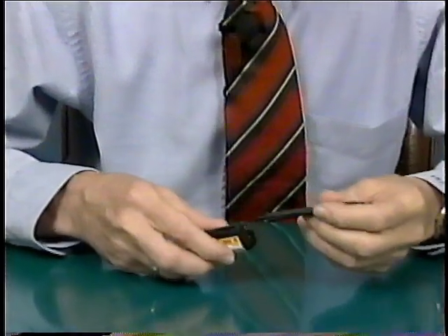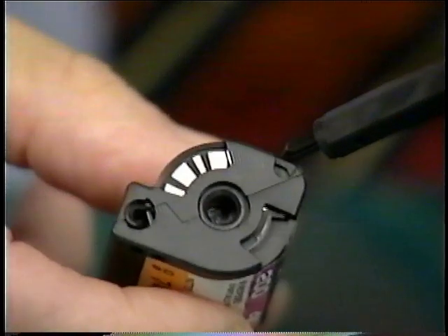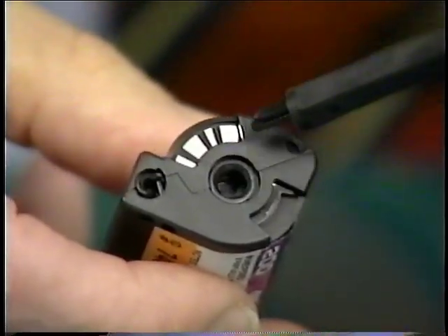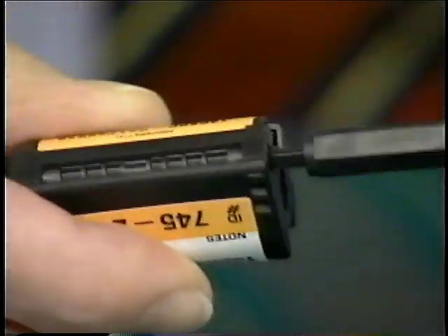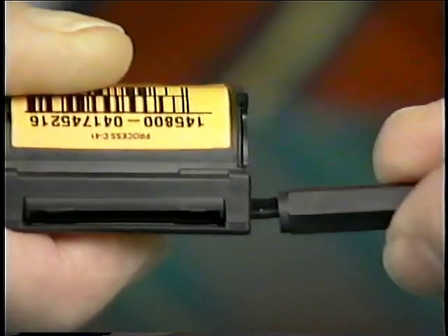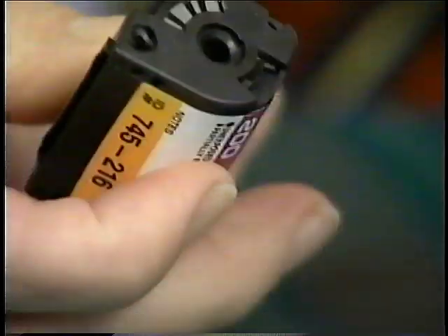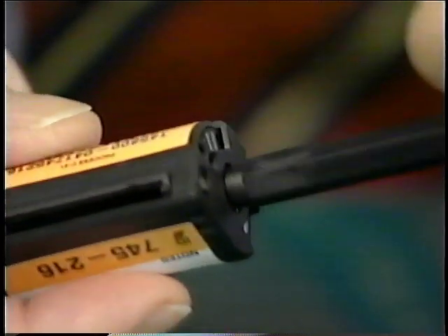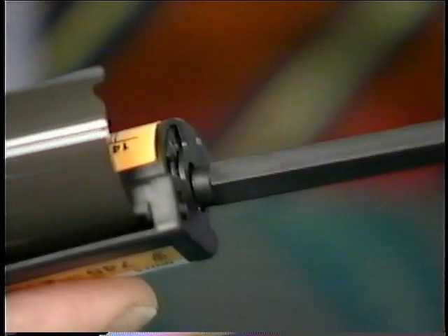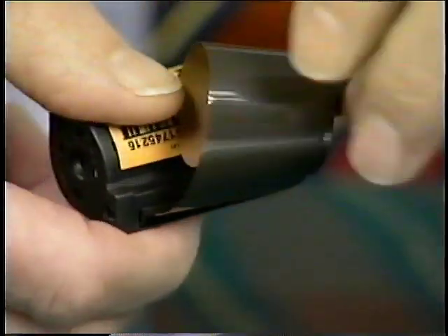Now let's look at the APS film and see what the differences are between it and 35mm. We're going to open the cassette, and I'm going to use a little tool here. And by the way, all the operations on the cassette are done at what would be the top end of the cassette as it goes into the camera, which is the end where the encoding is. But we'll insert the tool and open the light-tight door. You can see that just opens and closes. When the door is open, then the spool is unlocked and free to move. When the door is closed, the spool cannot turn without damage to the cassette. And we'll just turn in the direction of forward winding and just bring some film out.